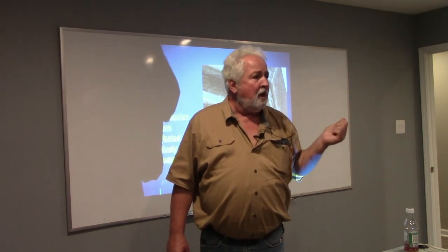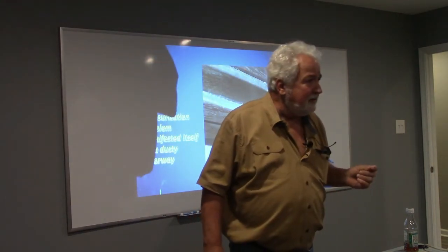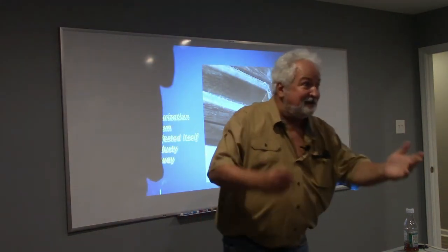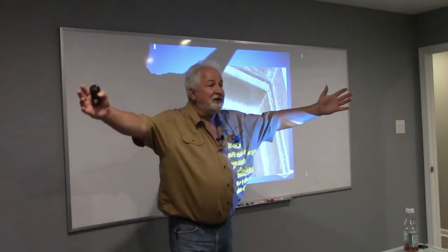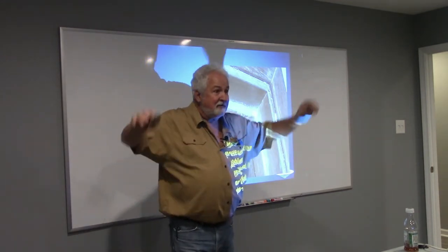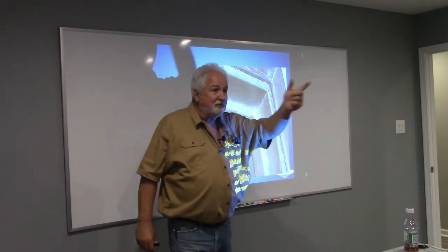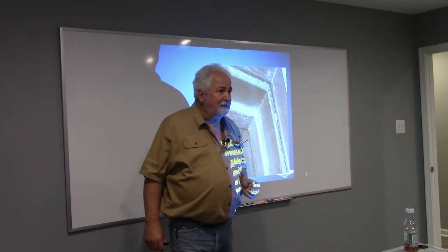So I'm going to pass my finger there, and I'm not going to say, look, lady, how dirty this is. I'm going to say, ooh, I'm seeing this dust here, which indicates to me that this door gets closed. Oh, yeah, we do close it, but only at night. How long is night? Half the day. Okay, so 12 hours. They've got this door closed, and we're sucking in moisture from the rest of the house, because that's positive and this is negative. We're sucking in moisture for half a day. How much moisture do you think I really brought in? A lot? You guys don't have any moisture problems on any of your houses, do you?